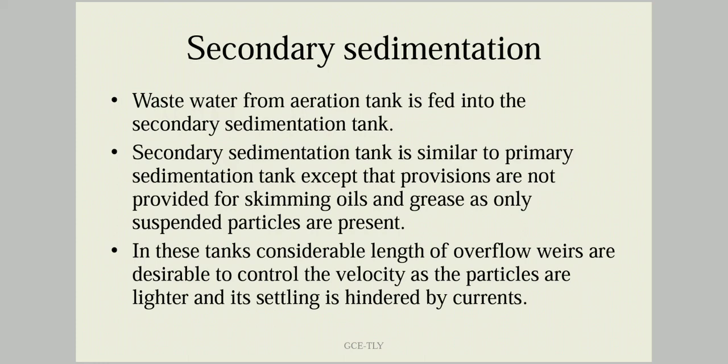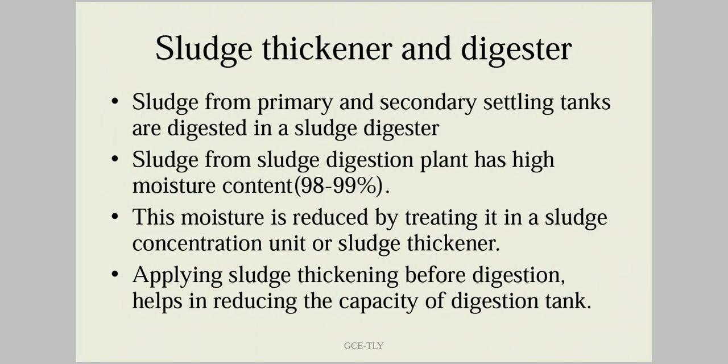Considerable lengths of overflow weirs are desirable to control the velocity, because the particles obtained are lighter and their settling is hindered by the current. So in order to obstruct the current flow, we introduce some overflow weirs along the length of the sedimentation tank.